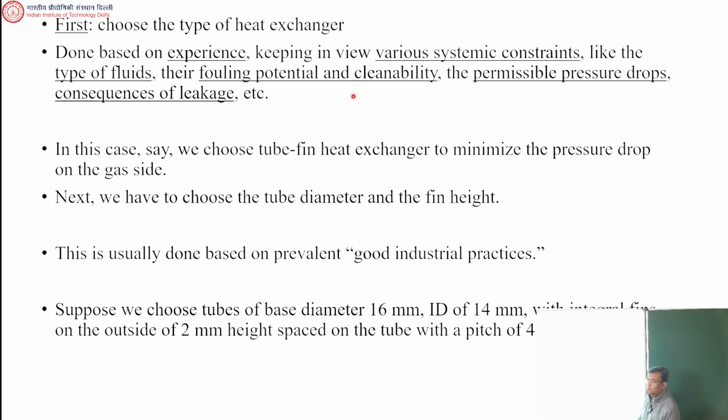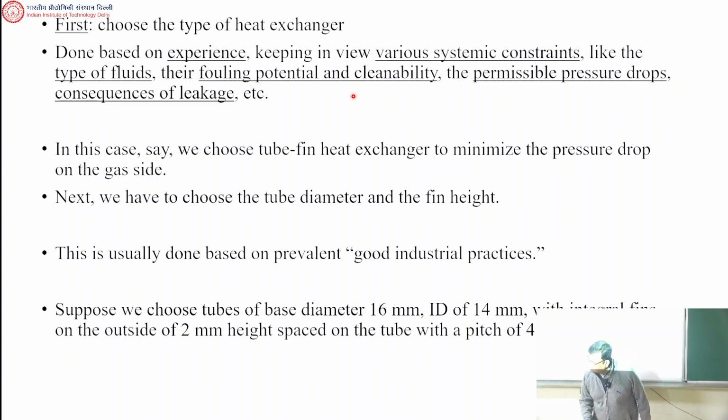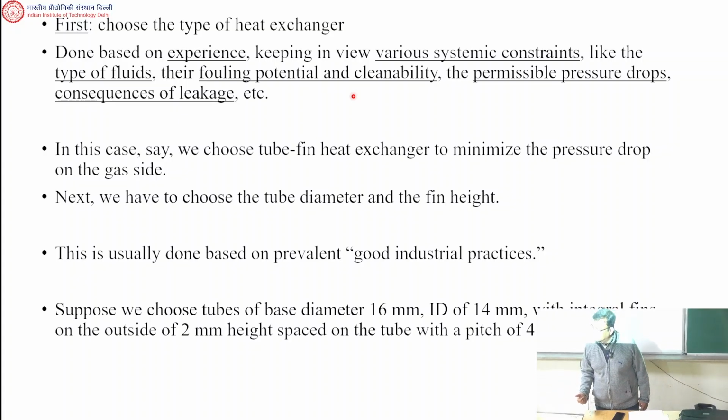Pressure drop is an important thing. You will know from this course, and you probably already know, that typically if you want to increase the heat transfer, what happens to the pressure drop? Pressure drop also increases. If you want to increase the heat transfer, it typically comes with a cost. The logic is like this: let's say you flow fluid over this. If you increase the fluid velocity, heat transfer will increase. But if you increase velocity, pressure drop typically increases, isn't it?